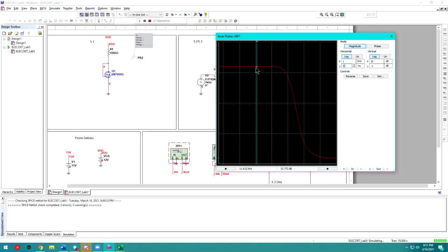So go ahead, take about 20 points of interest along this graph. Take more at the quarter frequencies where it actually moves here. On these linear portions you can take a lot less, but where the curve starts to happen, make sure you take a lot more points.